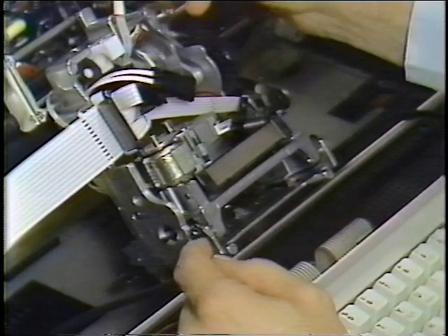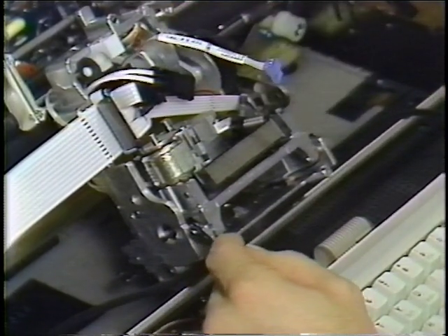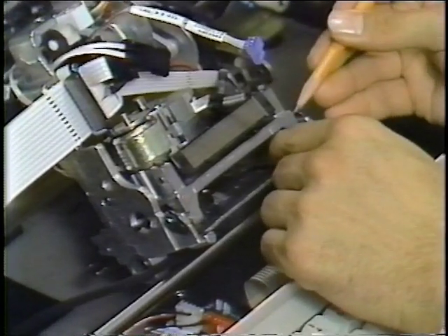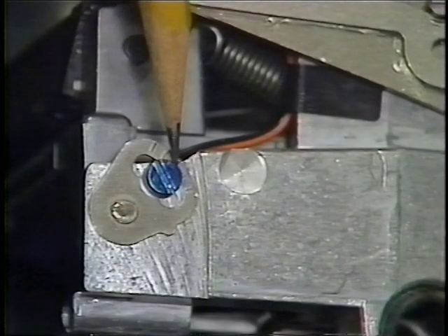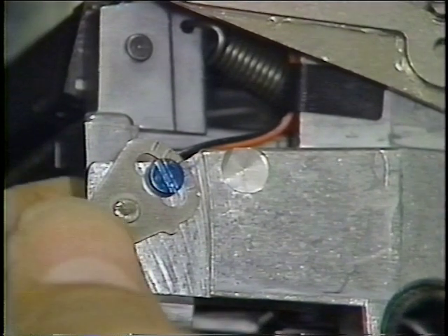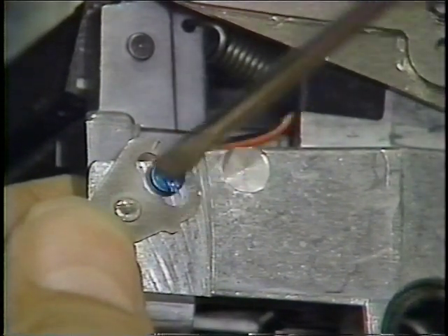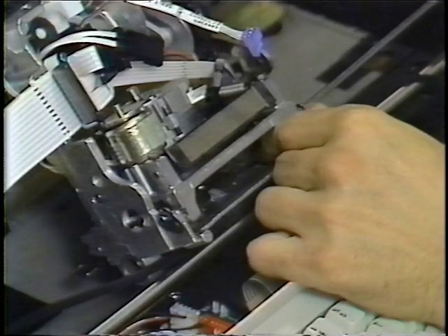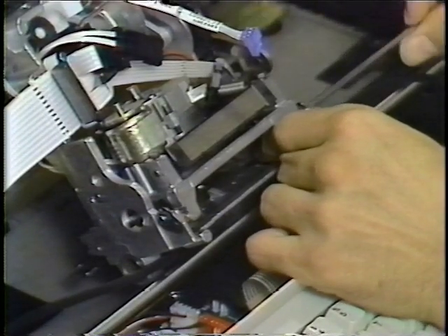Next, unplug the homing sensor connector from the bottom of the sensor bracket and pull the sensor connector cable out of the selection plate. Mark the position of the right-hand selection plate pivot eccentric by putting a pencil mark on the scribe mark that aligns with the carrier casting. Remove the right-hand selection plate pivot eccentric.